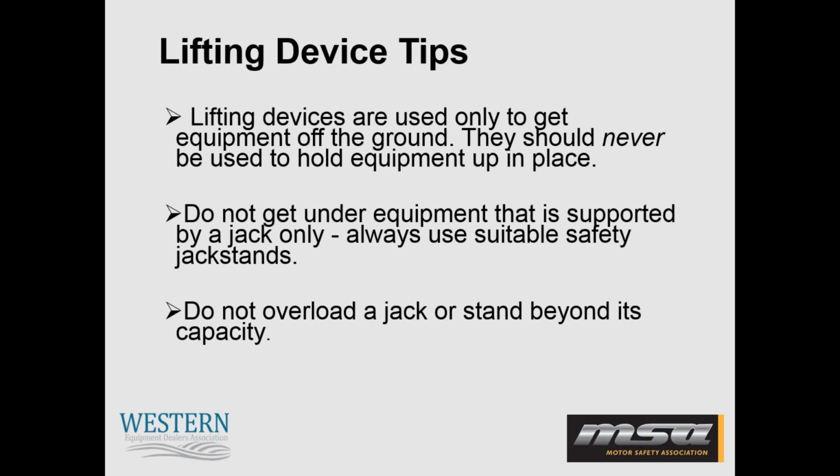Because you're never to go under a piece of equipment that is supported by a jack only. Make sure that it always has suitable safety jack stands in place before you go under any type of equipment. And as you're aware of, when we looked at the first case study from WorkSafe BC at the start of this webinar, we want to ensure that we do not overload a jack or a jack stand beyond its rated capacity.